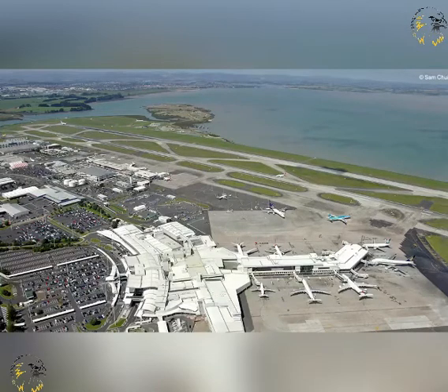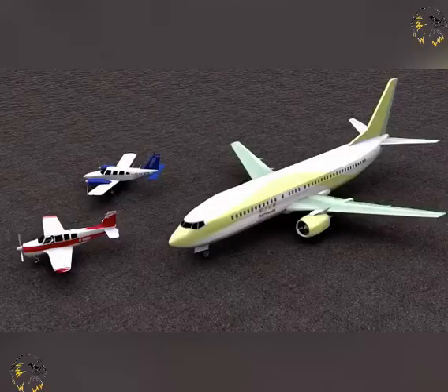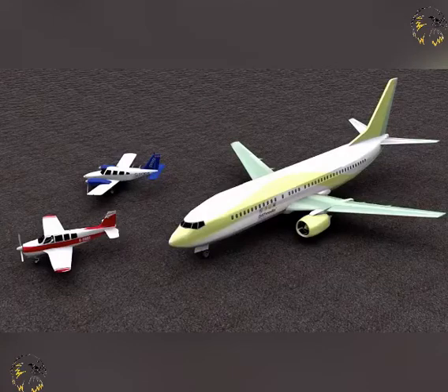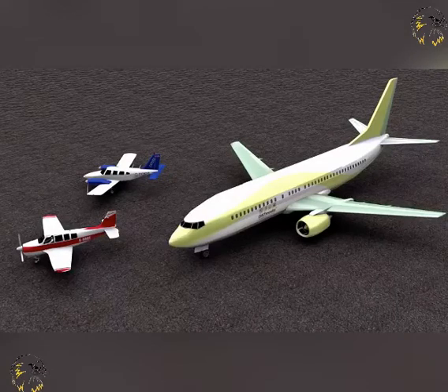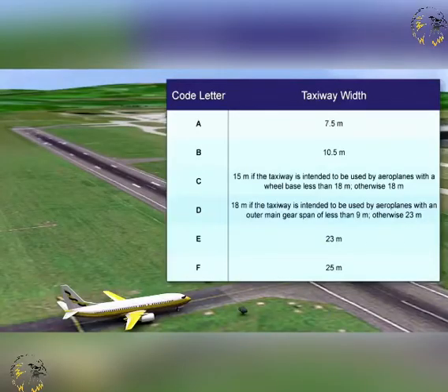Their load-carrying ability and width are major influencing factors in the capacity of an aerodrome to operate efficiently. The strength of a taxiway must be at least equal to that of the runway. Given the stopping, turning, loading and unloading taking place on them, they are more prone to damage than runways. Width is the most important factor to consider when designing taxiways, and the table shown here shows the minimum requirements for clearance of the outermost main wheels when the nose wheel is on the centre line of the taxiway.